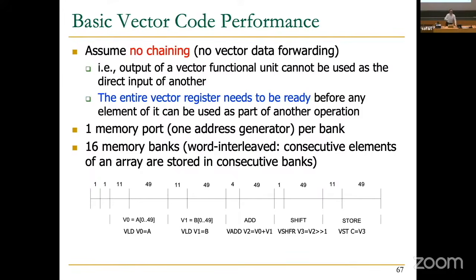And then it wraps around, of course, right? Because you keep interleaving across banks. But because your access latency is 11, your memory bank number should be 16. If your memory bank count was 8, you would have a stall of 3 cycles. You would service 8 requests and then stall 3 cycles, and then you keep doing that, basically. But that's not what we depict over here. Okay, so that's vector load.